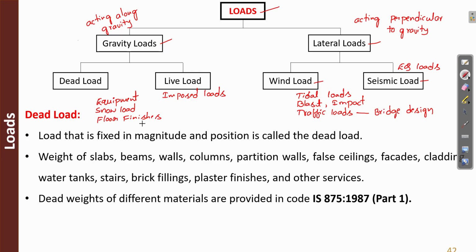For dead loads, we follow IS 875 part 1, that is 1987. For live loads, IS 875 1987 part 2.